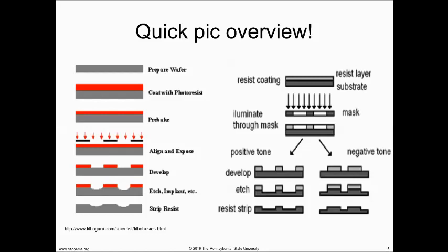That would be the etching part, or an ion implant, because I know other people have talked to you about making a transistor and doping and all that. So that would be our dopant mask and stopper. And then finally, at the end we always remove the photoresist so we can do the next step. So lithography at large is a transitional step that we do temporarily to define the pattern. Once we define the pattern, we have to clean off the photoresist and start a new pattern to go to the next level.